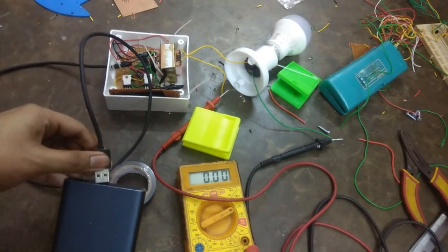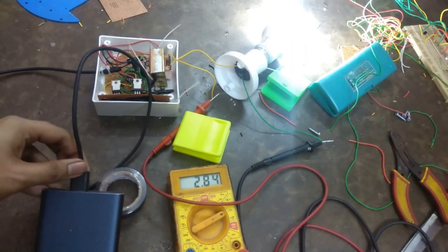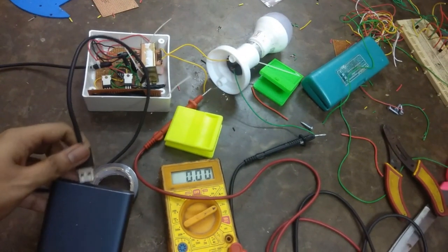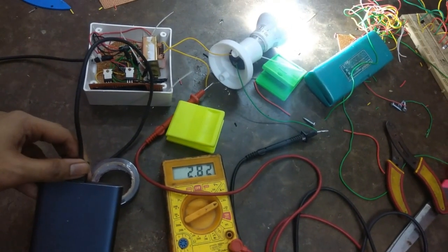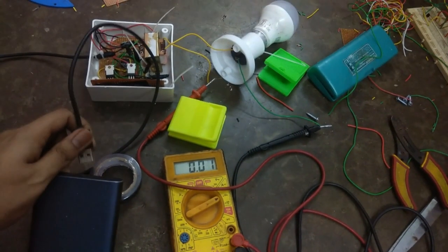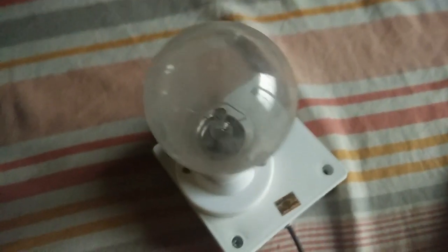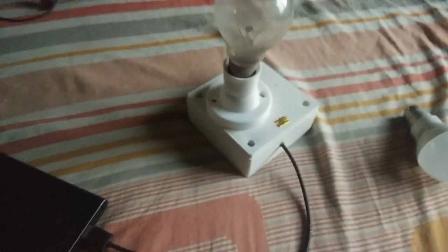Word of caution, this is not a very efficient circuit. A more efficient circuit can be designed. Normally it is a very robust circuit, you can change the bulb and you don't need any heatsink, but the circuit is not very efficient. Here I have used a 60 watt Philips incandescent bulb, and you can see it is not lighting up because the circuit cannot deliver so much power. But with the LED lamp, it can deliver enough power such that it lights up.